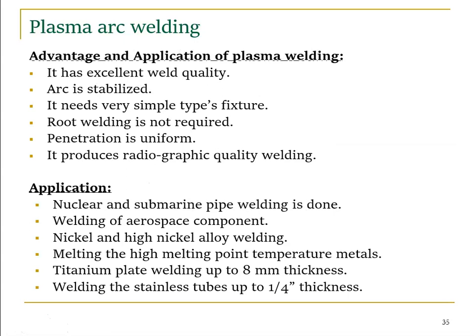So advantages are it has excellent weld quality. The arc is stabilized. It needs very simple types of fixtures, so very simple holding. Root welding is not required. Penetration is uniform. It produces radiographic quality welding. Applications are nuclear and submarine pipe welding.